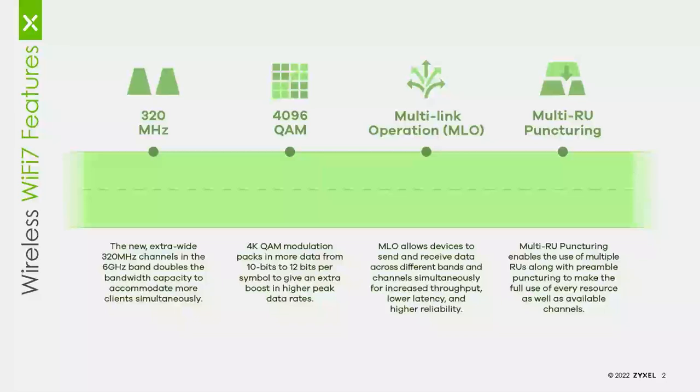With Wi-Fi 7, we can take that 320 megahertz channel, split it in two, and ignore the part that has the interference. So instead of 320 megahertz, you now have 300 megahertz with no overlap or interference. So it allows you to use those wider channels and take the benefits of using them without the risk of greater interference like you had in the past with older Wi-Fi technologies.